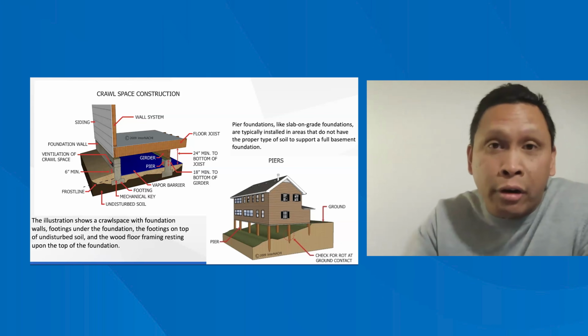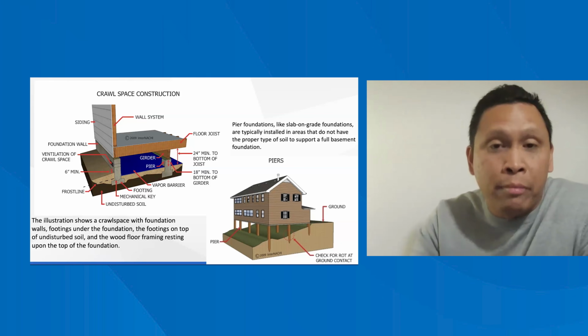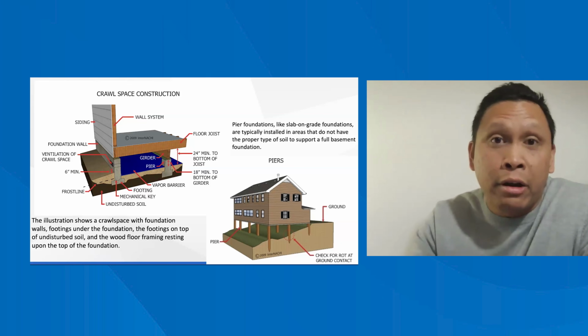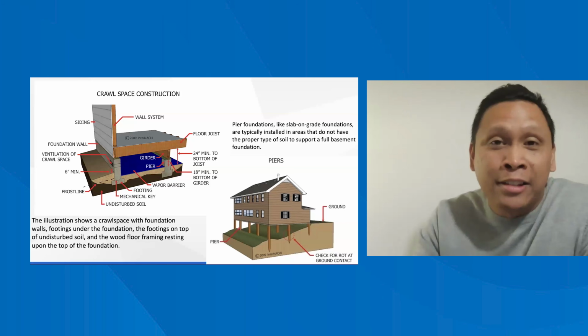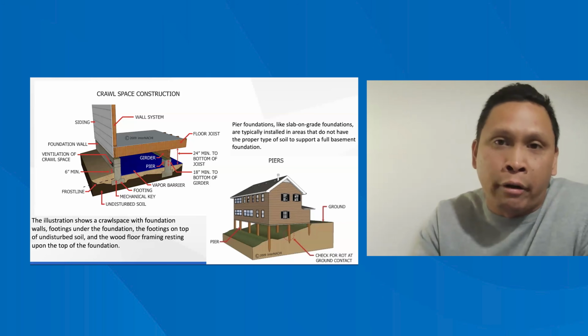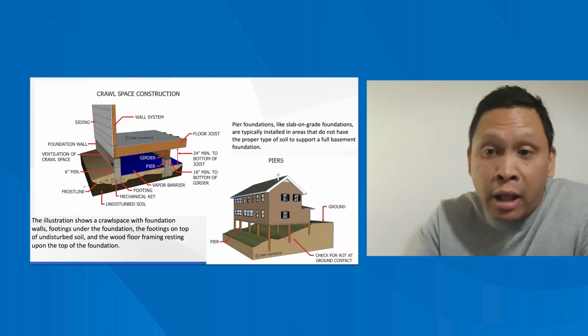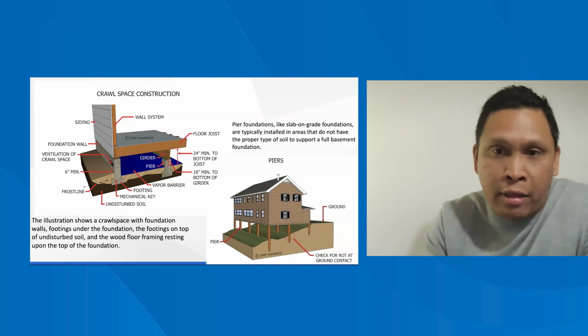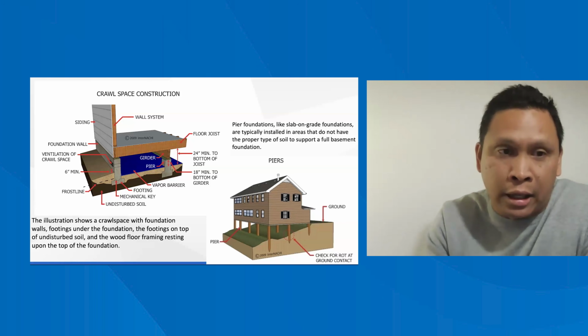But you could see standing water in the crawl space that is now impacting those structural components of the home because no one knew about it for years. And then you go in, because now the home is built, and you say, why is this support leaning? Oh, look at this standing water coming from the sewer drain line. So very, very important, if you think it's safe to do so, make sure you get a good sense of the overall condition of the crawl space, to make sure that the family, or your client, has a good understanding of what they are actually getting into.